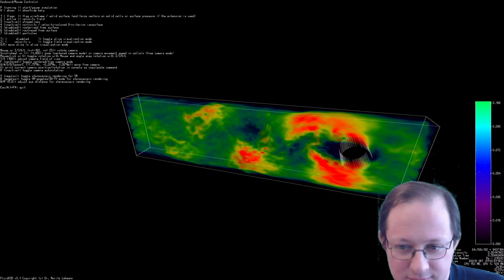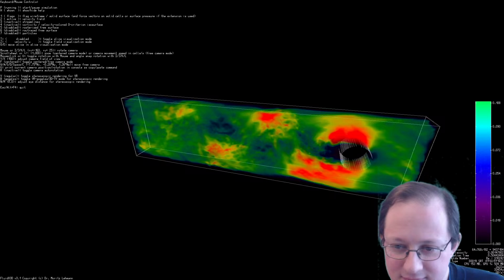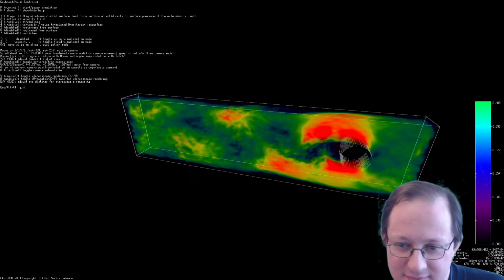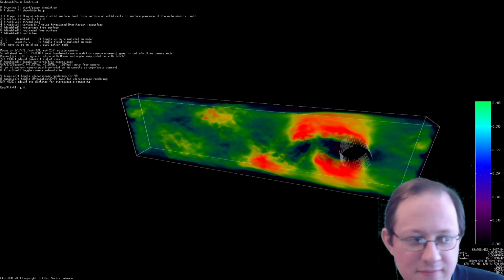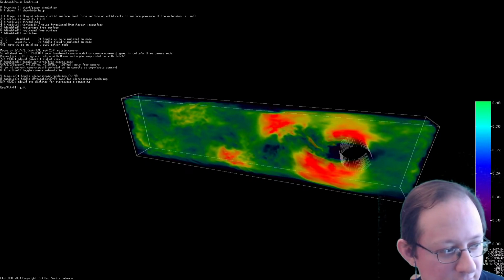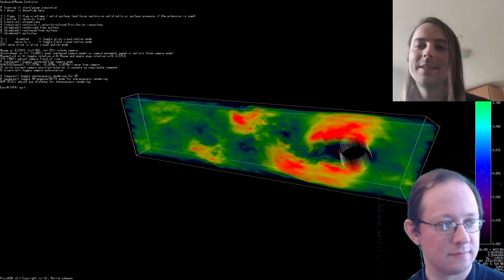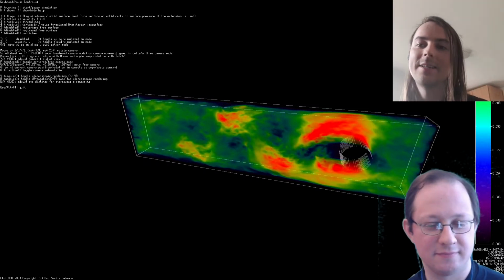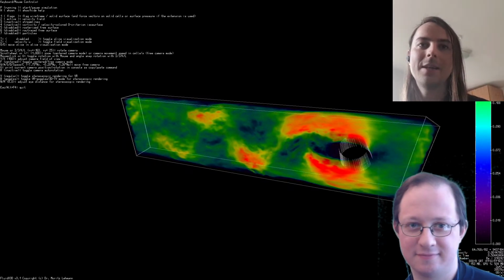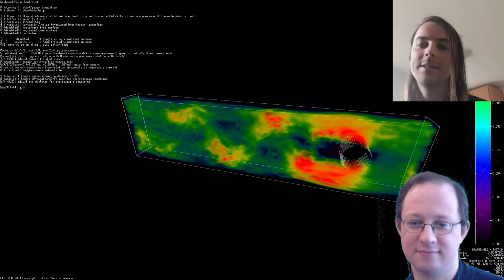I experimented a lot with different rendering approaches, and this ray tracing based velocity visualization was actually brought up by one of my users. He had the idea to do it, and then I was experimenting with it a little bit myself. This is actually doing volumetric ray tracing. It shoots rays out of the camera, and they intersect through all of the grid cells, and along the rays, the velocities are probed, and then the color is determined based on different weightings.